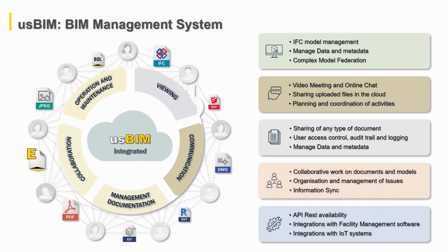It's an integrated environment where the entire BIM process can be managed, including managing models in the buildingSMART standard formats, such as IFC, instead of native ones, federating both BIM model geometries or simple geometric models like point clouds or textured meshes. It also includes collaboration tools like an instant messaging service and video meetings where the BIM data and models become the topic of discussion. It also allows data and document sharing through a system of articulated access permissions and information tracking pertaining to operations carried out within the platform.